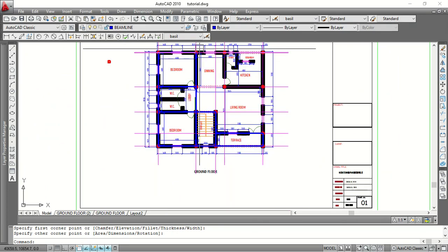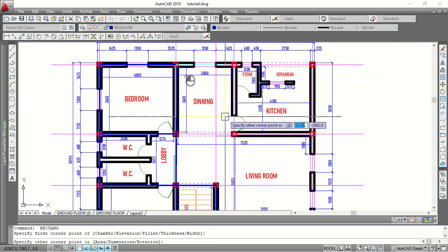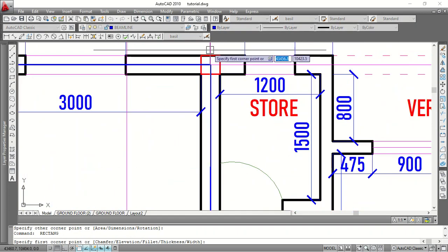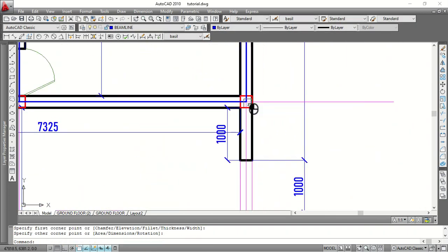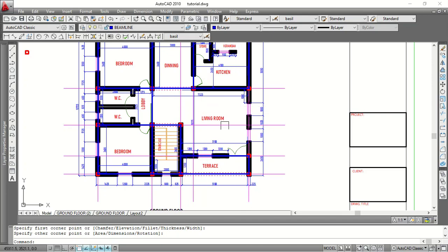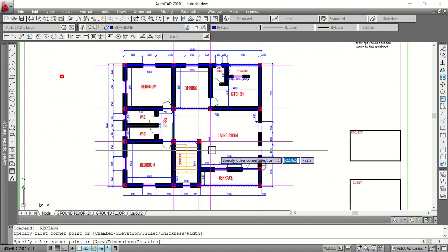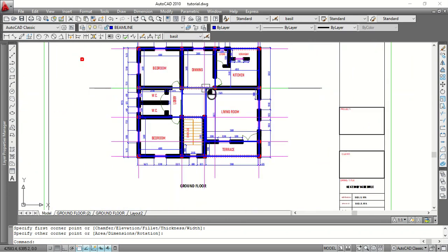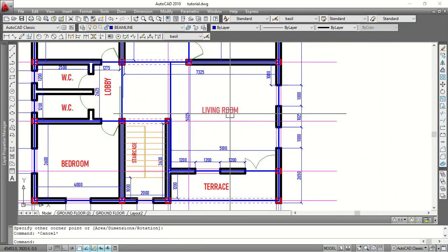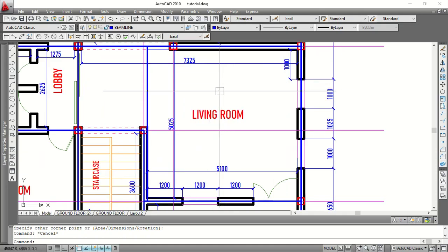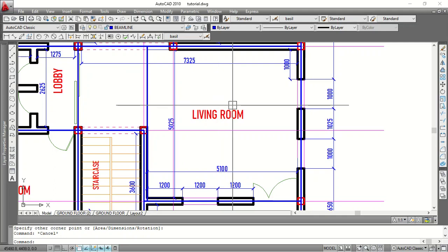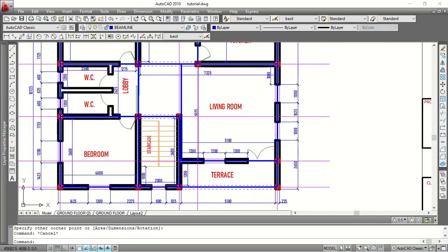One after the other. So I'm left with this now. Okay, so this will now come from here to this point. So I was trying to say something. You know, if you're a structural designer, you've done series of designs, you discover that trying to design this using, let's say, a floor thickness of 150 will stand to fail deflection, except you have to apply some other principles, okay? Because of the floor area.